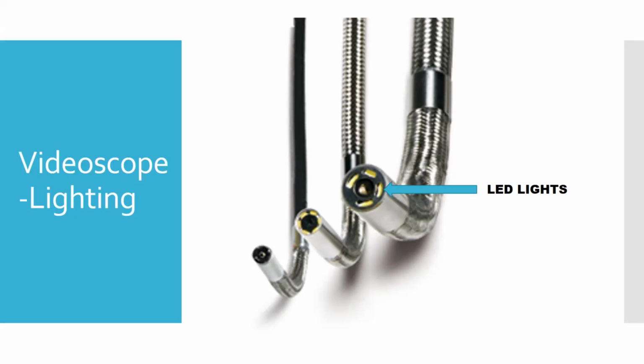Maybe you put the tube where a fuel nozzle goes, and it's basically the same shape as a fuel nozzle, and then you can feed your scope into it, and it routes your scope down into the combustion chamber, or any number of other places, designed to route the tip of the scope to the correct spot where you can see what you're looking at.